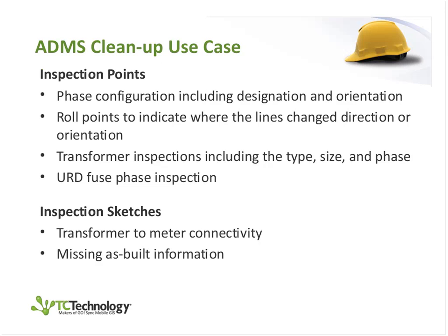On top of that, because you're tracing out that phasing from the substation, you can follow the phases and identify what phase a transformer is connected to, what phase a fuse is protecting. So in doing that, you can ensure that the protective devices and the transformers that are feeding the demand points are going to be on the proper phase.